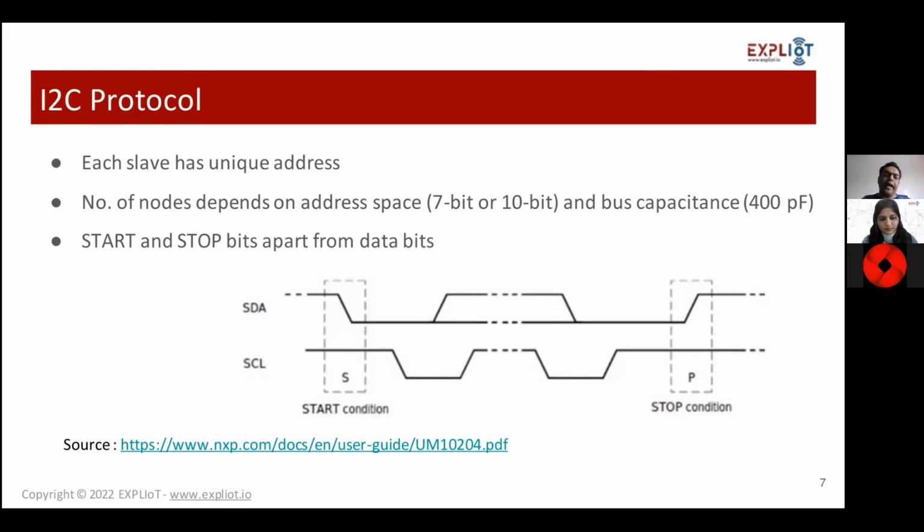So whenever any device, any sensor or peripheral, comes with the I2C bus interface, it will have a specific address. Depending on the characteristics, it can have either 7 bits or 10 bits of address. Most commonly you will find 7 bits of address. You may wonder why 7 and why not 8, because we have that standard of 8, 16, 32 in our thought process of the logic.